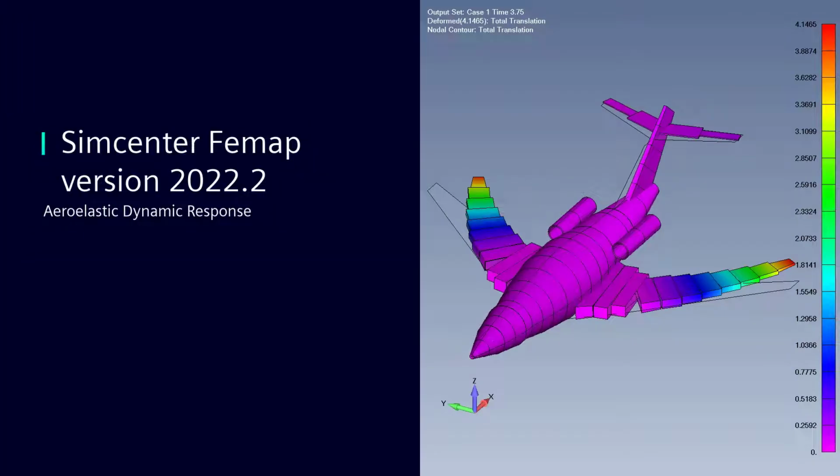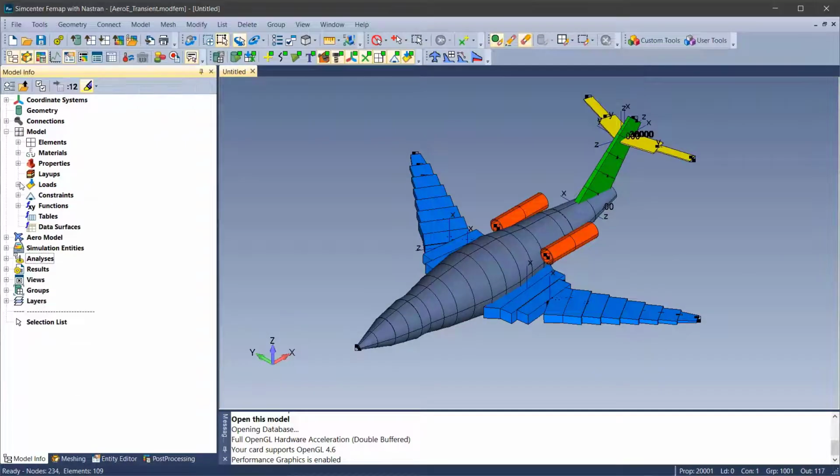Simcenter Femap version 2022.2 adds support for aeroelastic dynamic frequency, transient, and random response, in addition to its long-standing support for static aeroelasticity and aeroelastic flutter. This model is used to simulate aeroelastic transient response.